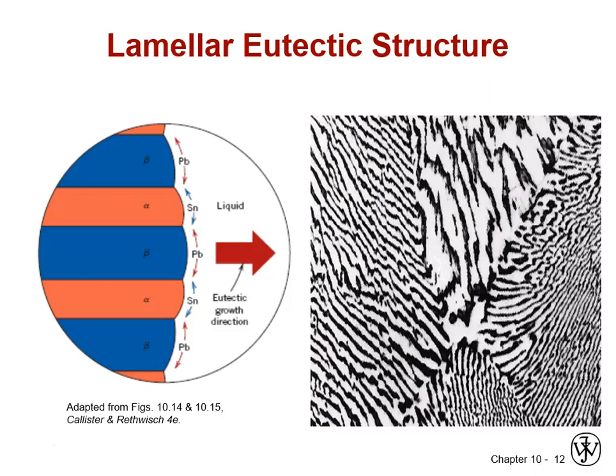And then in the case of the beta phase, lead is being driven to the sides and forming a lead-rich alpha phase. So they're literally swapping places in the liquid very quickly, and when they get to their concentrations, all lead or all tin, they form a crystal with very little of the other in it, and then that layered structure of almost pure lead and tin alternating layers moves forward.